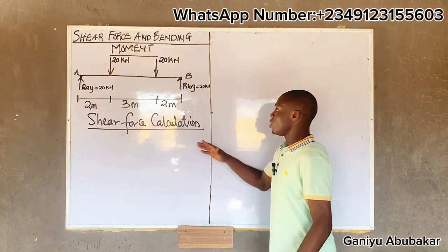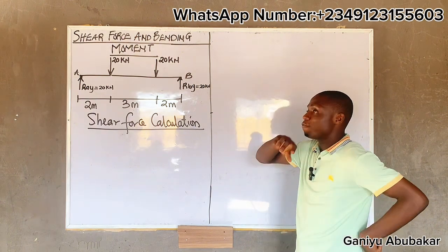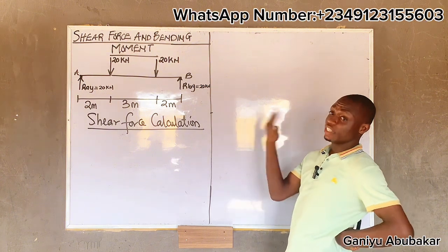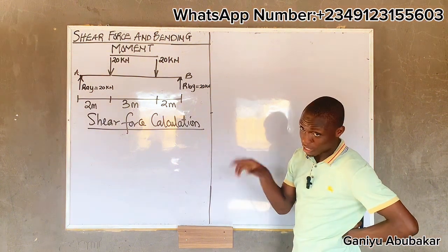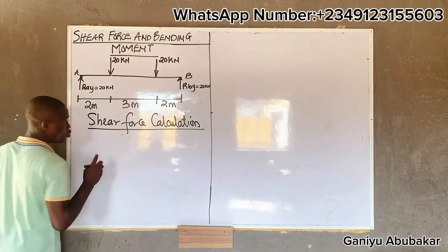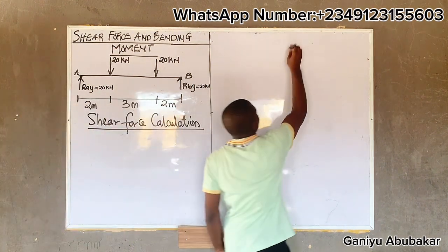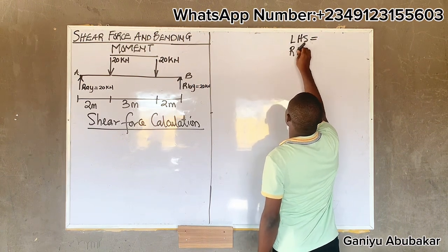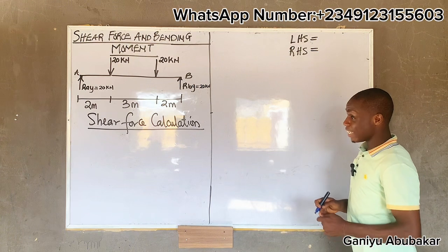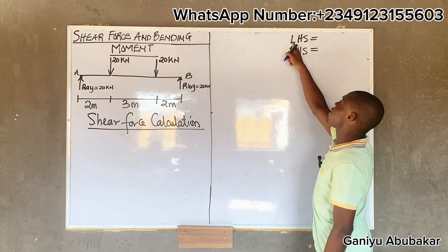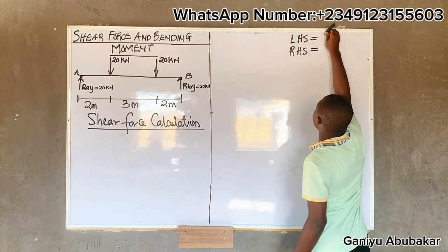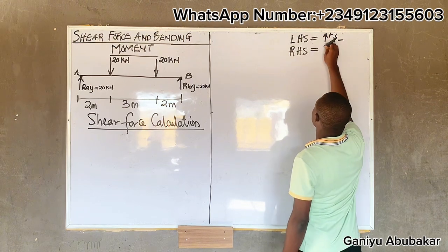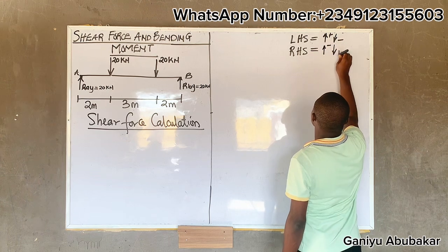All right. Look up for shear force. Shear force is in two conditions. Either I choose to go with left hand side reading or right hand side reading. What do I mean in essence? If I'm going with left hand side, I should expect that upward is positive, down is negative. If I'm going to the right, up is negative, down is positive.